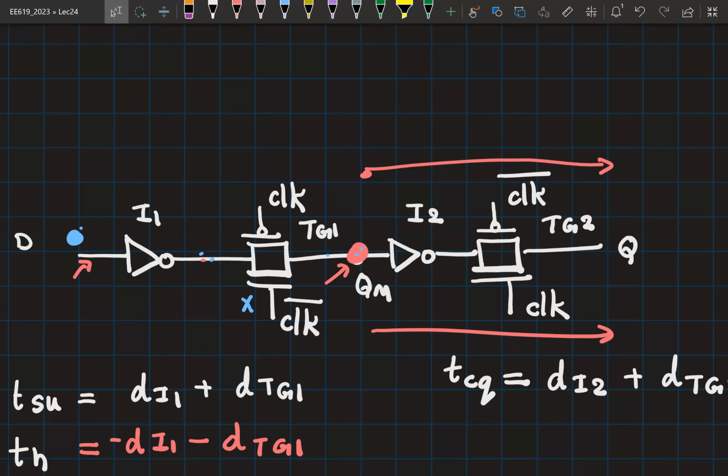And what do we mean by an issue here? We expect the output to change corresponding to a rising edge in clock alone. Corresponding to rising edge in clock, it should sample the data that has been set up and held correctly at the input. If any other change happens at the output, we have a problem, right? So that is what we want to check. So quickly tell me what is the sampling edge here and what is the non-sampling edge.